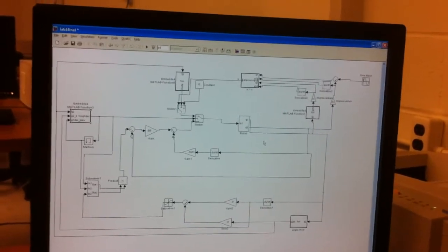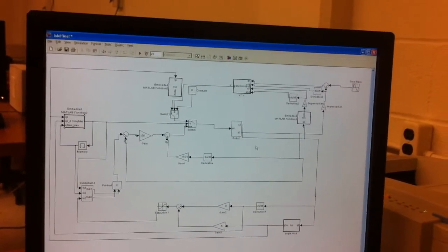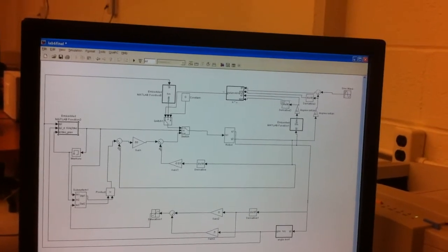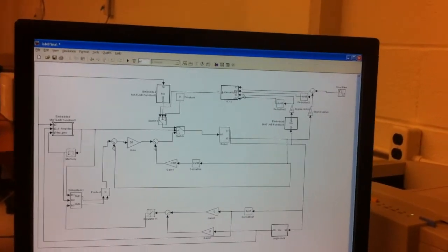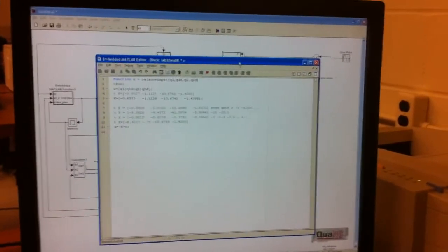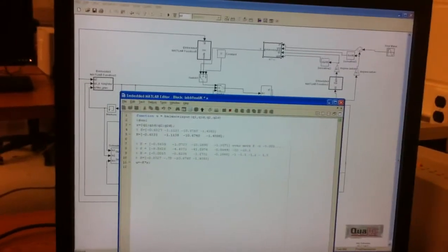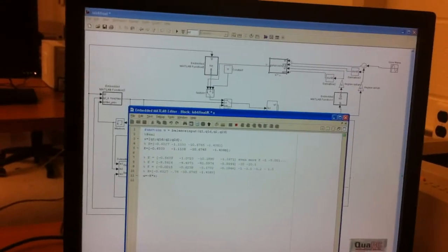So we set our poles for that at about -5, and all of them on top of each other, or almost on top of each other, so that we had a critically damped system, or as close to a critically damped system as we could have.